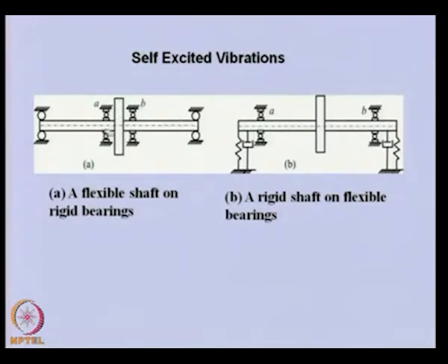If we rotate this rotor, then it will start whirling. If these bearings were not there, it would start whirling because of the unbalance. Now if we want to stop the motion of this disc, we provide two bearings very close to the disc. Obviously the motion of the disc will be arrested. There will not be any vibration, because now this rolling bearing does not allow whirling of the disc. But because the shaft is rotating, the unbalanced force will still be there in the system. It will not diminish because of stopping the motion.